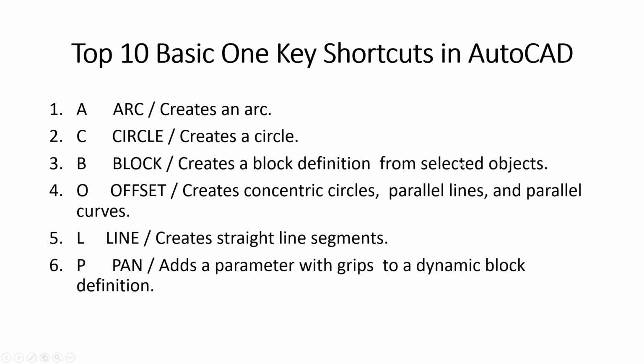Next, we have P for the pan tool, and this creates a grip where you can pan around and move around to look at various areas of the drawing or drawings. Let's look at this.